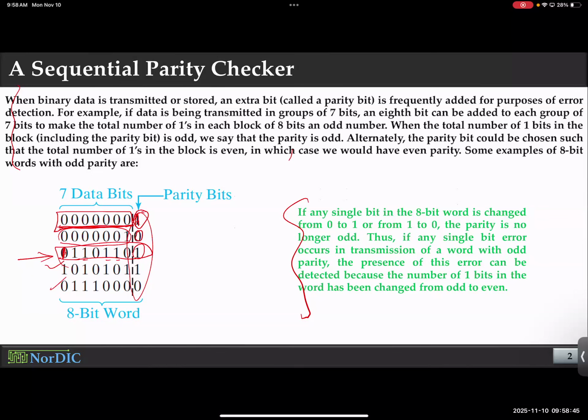Of course, you cannot pinpoint which bit flipped. Did this one flip or the other one flip? What you do is you ignore that entire chunk. 7 bits is not much, honestly, but you see my point here. So you always have a set of bits and you have a parity checker. If you do it more often, then you'll be wasting a lot of bits because these are essentially useless, except for the checking,